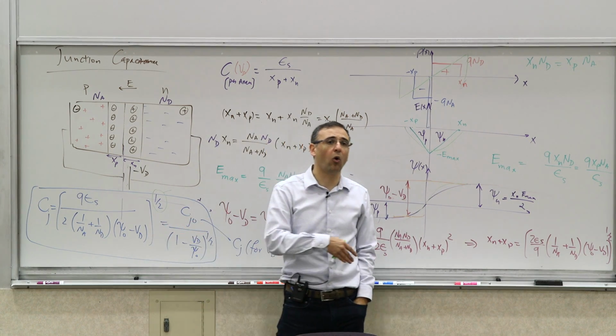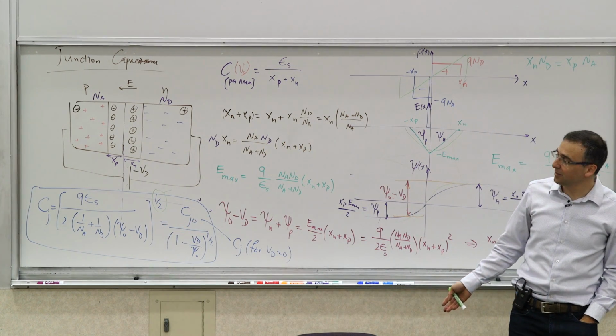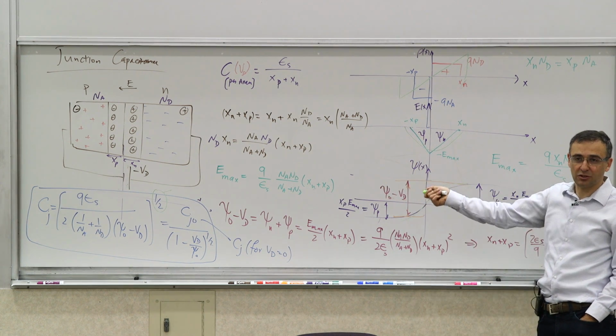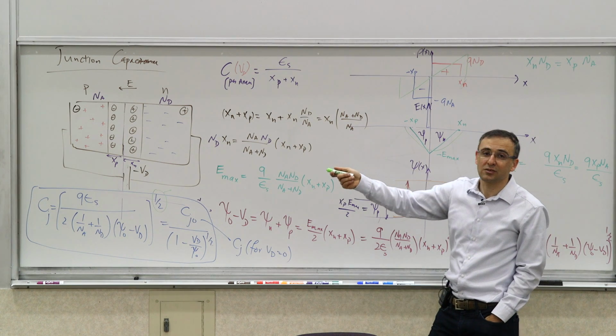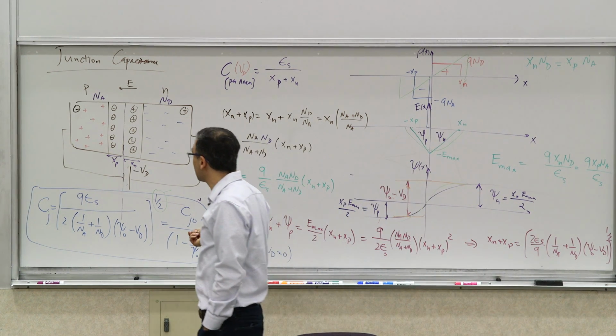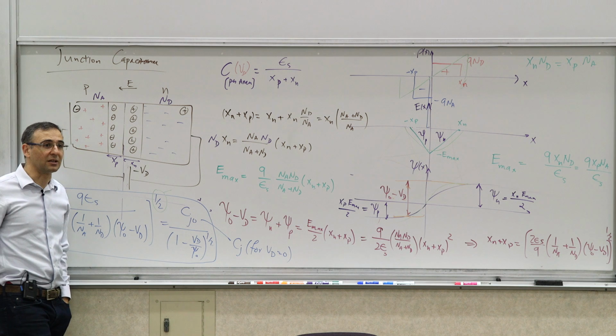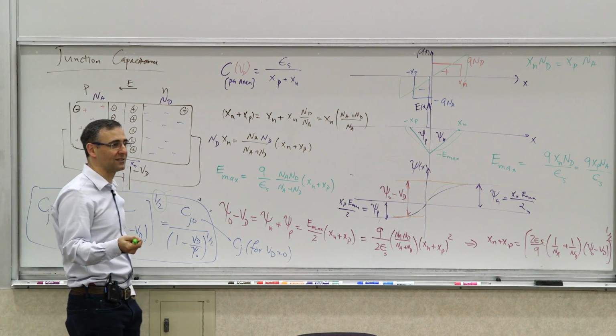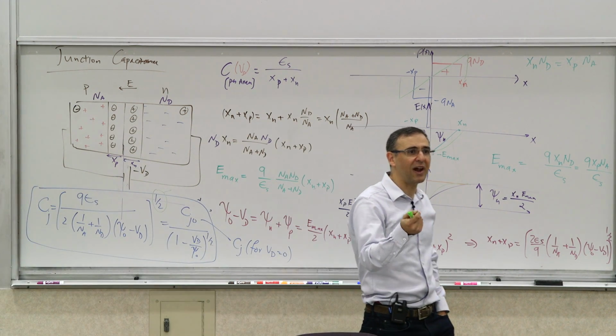There are also a whole bunch of other nonlinearities in the devices, right? I mean, for example, you have an exponential current-voltage behavior, and things of that sort. But this can contribute to the nonlinearity if you take care of some of the other things. Now, it can be a good thing if you're looking for a nonlinear capacitor to do something. For example, if you're looking to change the capacitance, you are looking for a voltage-controlled capacitance, right? It's called a varactor.